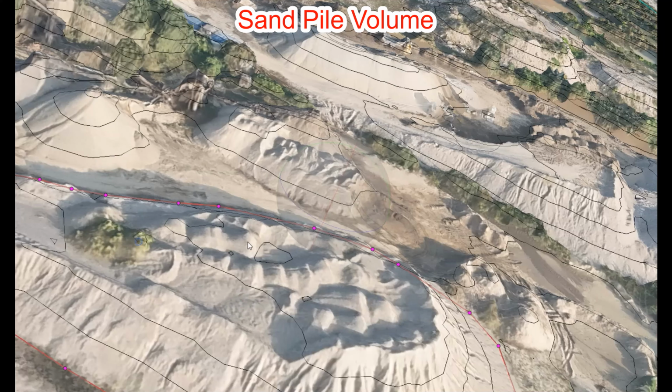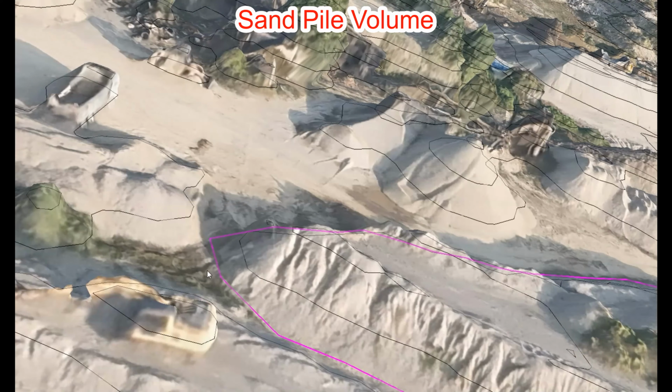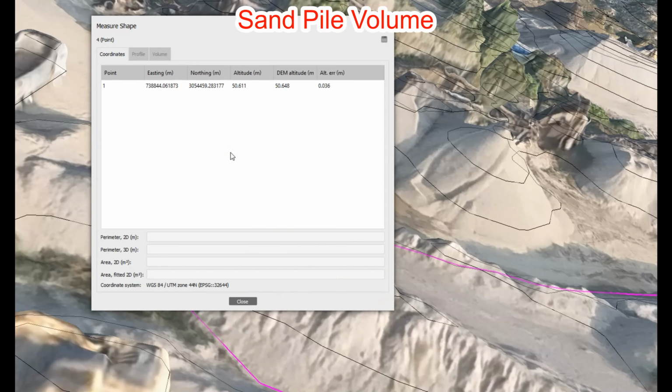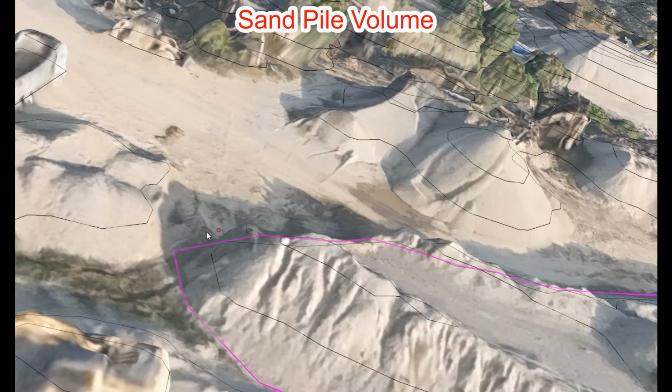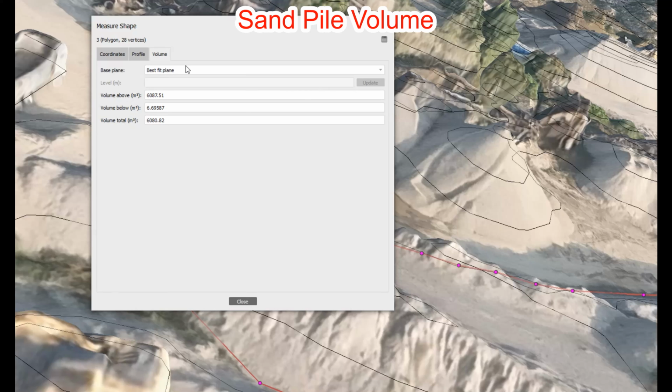Similarly, if I want to calculate the volume using some reference level or the ground level, then I can go to draw point and draw one point. Okay, I draw one point here, right click and measure, and it gives the elevation of that point, that is 50.648. Now I will select this polyline, right click, and the value 50.642.